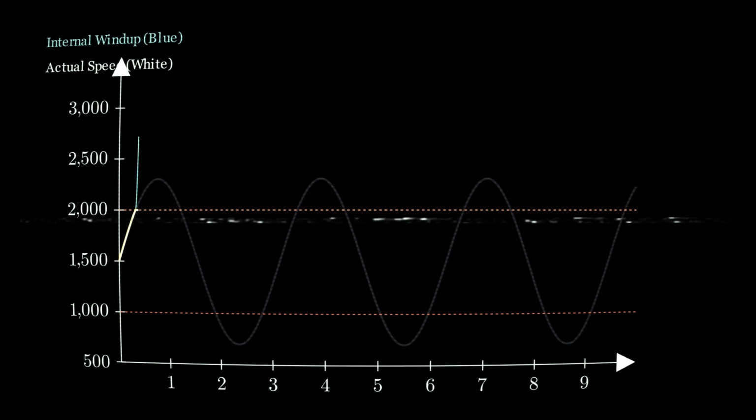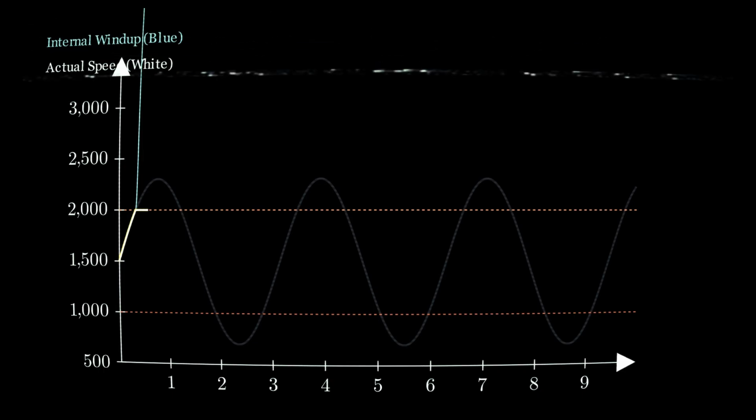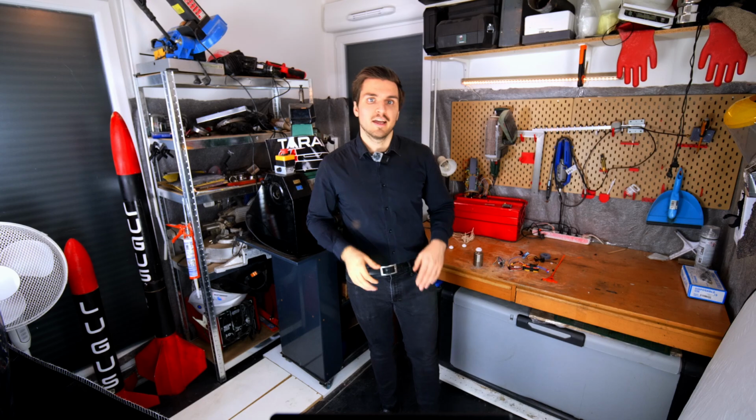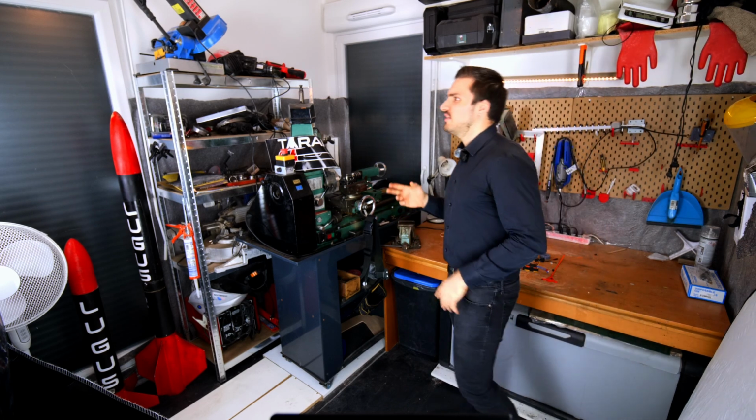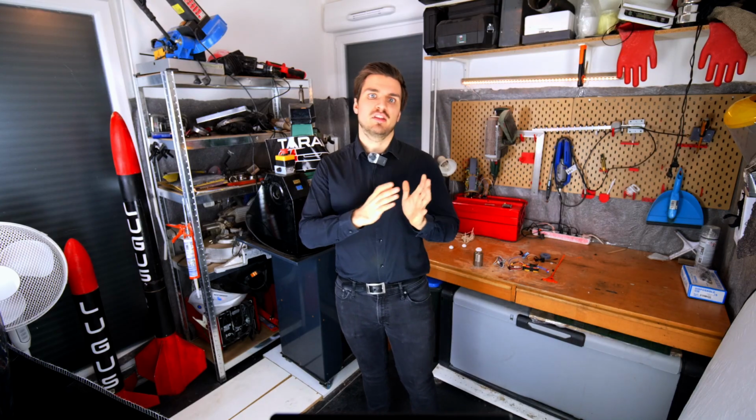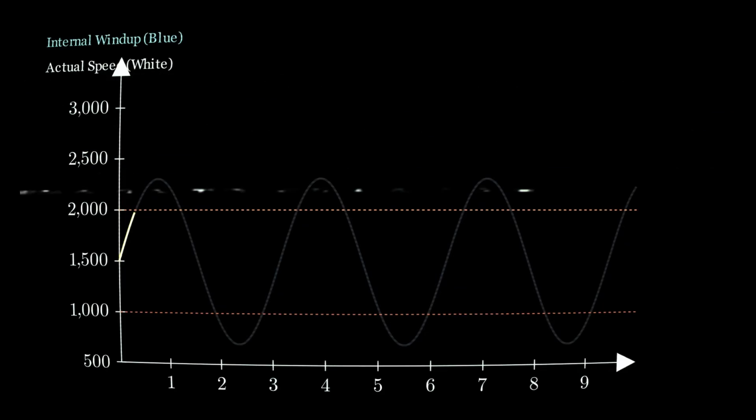Imagine you have a rolling machine that starts and you activate the motor at full power, but quickly you will reach the maximum that your motor is capable of providing. However, your system did the job, in the sense that the rocket gently begins to slow down and return to a speed command range that you can manage. Except that during this time, the integrated error, which is constantly being added, keeps accumulating. But since the motor is at maximum speed, there's nothing we can do but wait and accumulate even more integral correction.